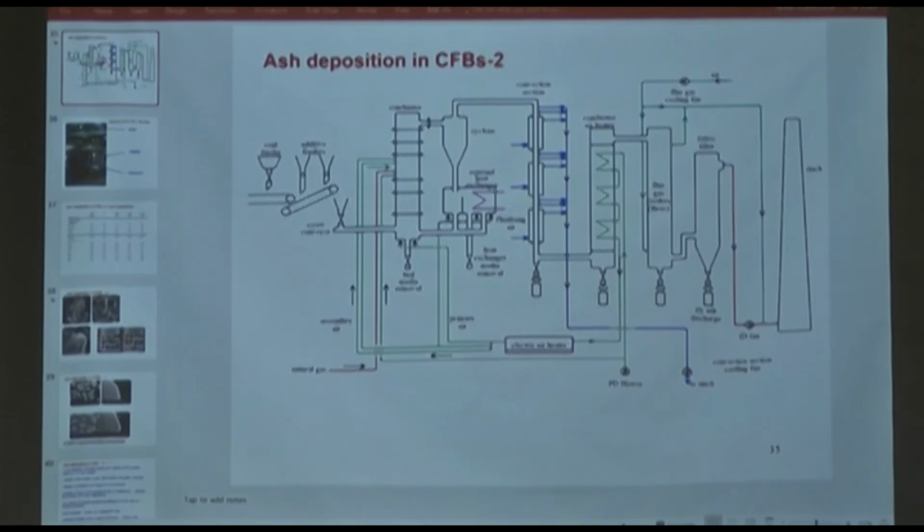It will either drop or increase significantly, and you can actually see on the screen in the control room, if you are sending all the thermocouple signals to the control room, which thermocouple is misbehaving. So bed agglomeration, that's what it will do to the thermocouples.